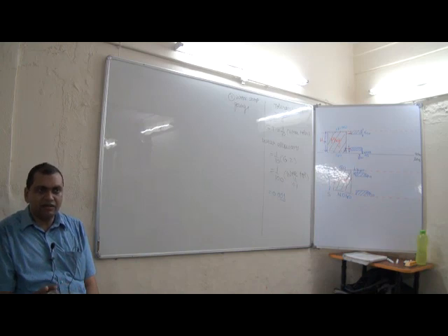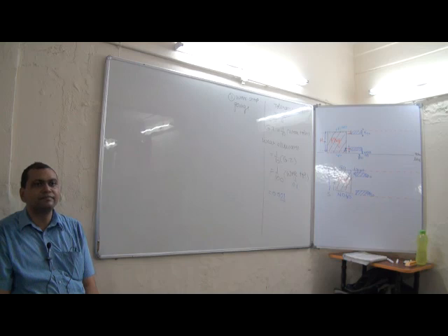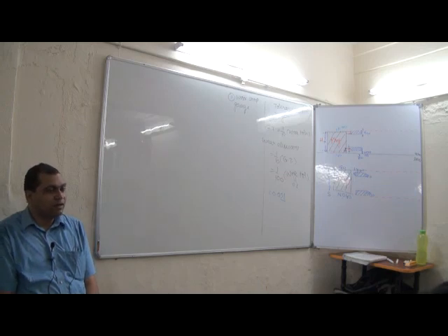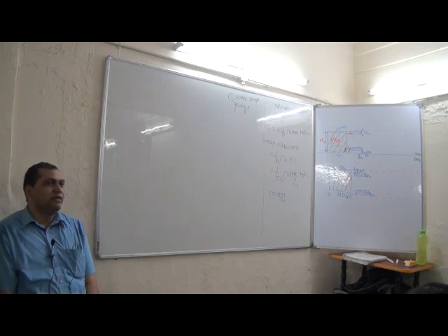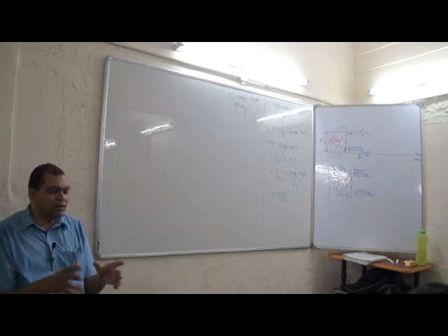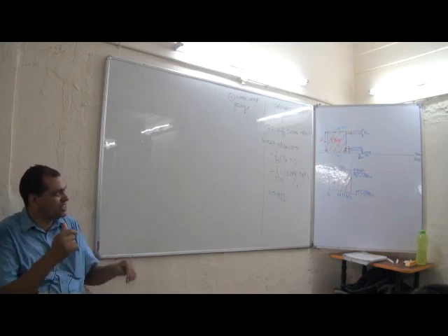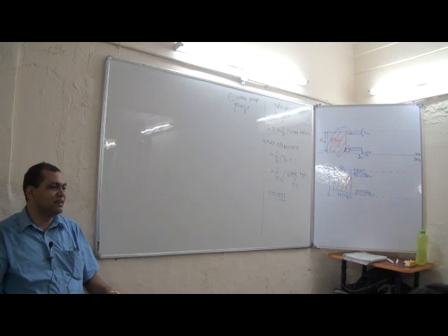Take your time, okay? If there is anything, again I will explain. Any questions? You have questions? Extreme cases means? No, you will not say extreme cases, you can say the holes that are appearing close to the tolerance limits. Close to the tolerance limits, they will be rejected by the gauges. Okay?